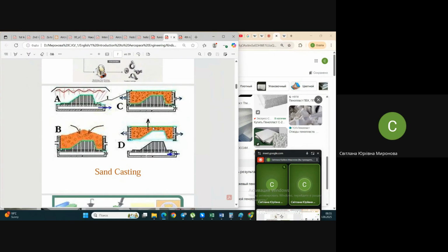And as soon as you reduce the temperature of this molten metal that should be poured inside and distributed equally all over the mold, as soon as it has contact with the surface of the mold, it starts solidifying. And the problem is that it may create something like inner barriers, and it may make other metal stack up again inside the mold, and the mold will not be poured properly. It's like the metal interrupts the process of pouring because it was too quickly solidified.